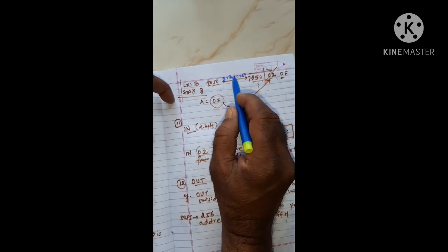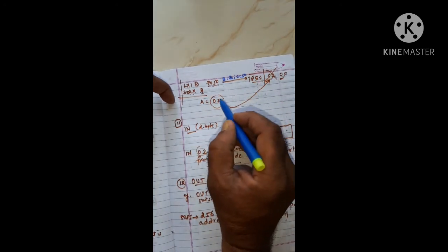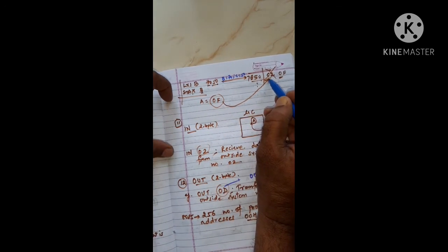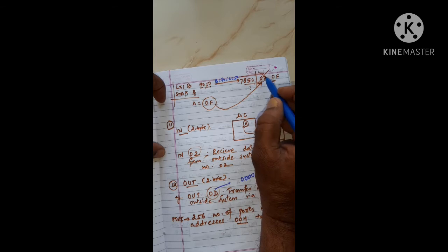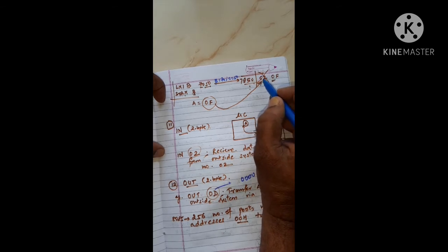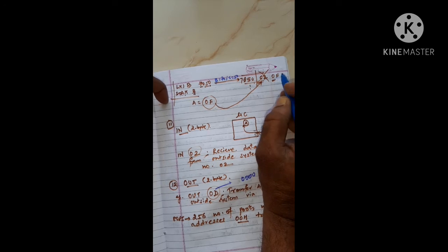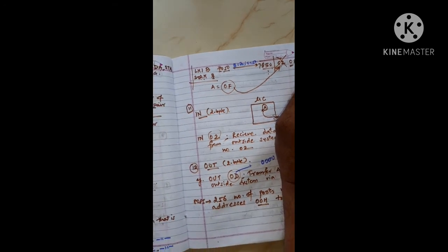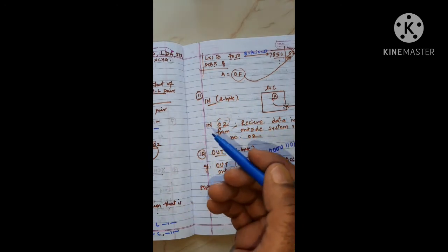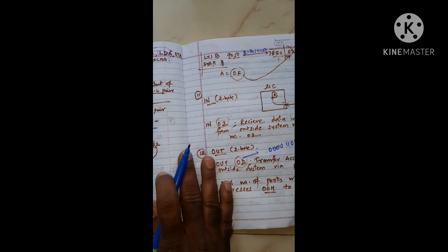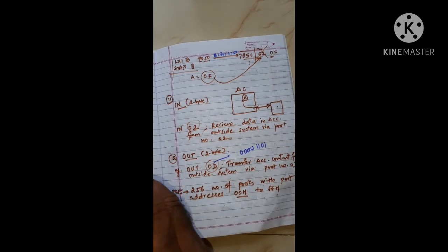The BC pair initializes location 7050. The content of A will be shifted as it is to this location. So as an output, instead of C2, we can observe 0F as the new content. So these are the ways to transfer content of a location to the accumulator or content of the accumulator to any location.